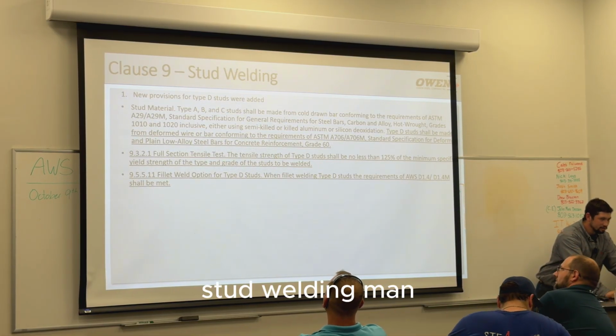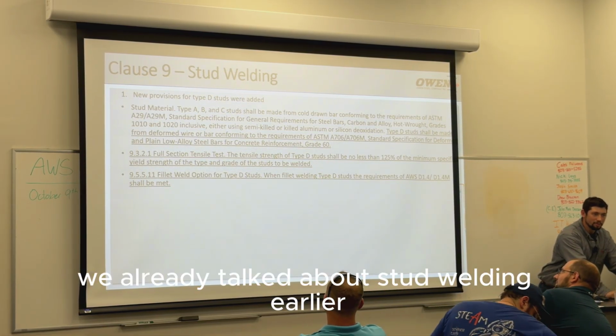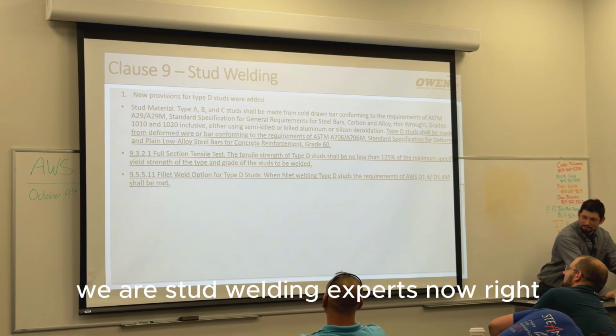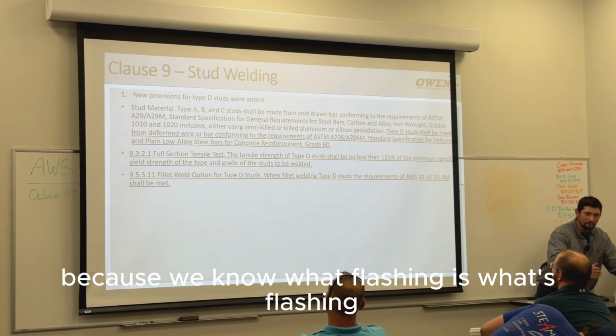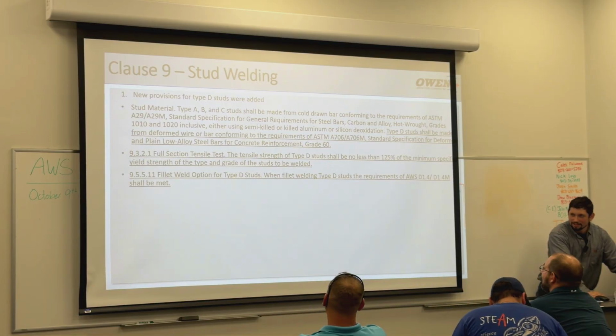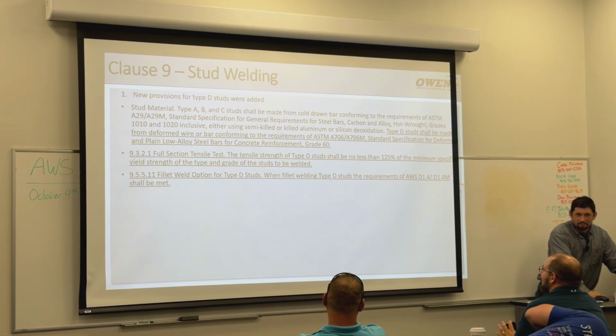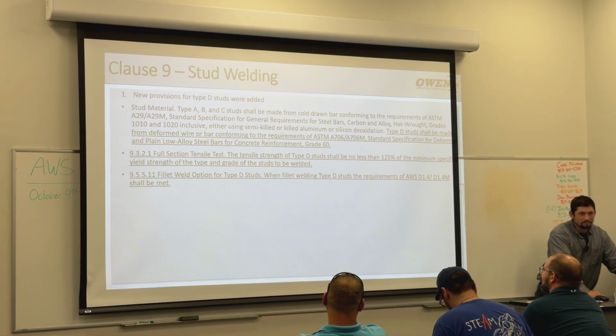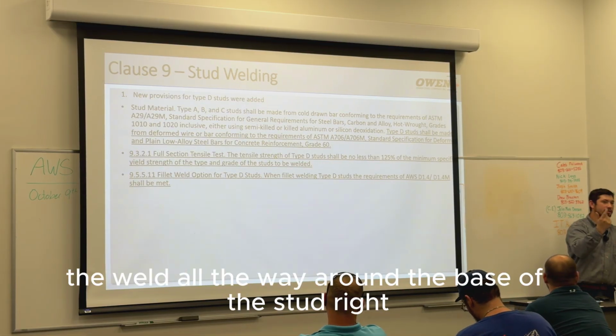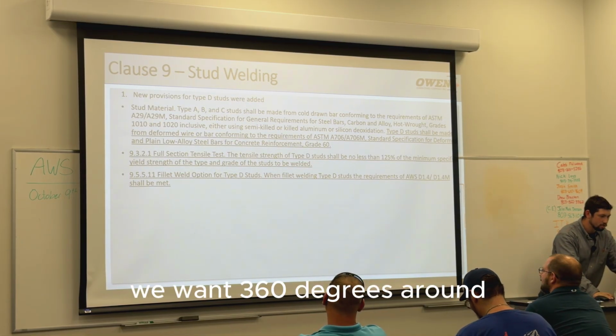Stud welding. Man, we already talked about stud welding earlier. We are stud welding experts now, right? Because we know what flashing is. What's flashing? Yeah, the weld all the way around the base of the stud, right? We want 360 degrees around.